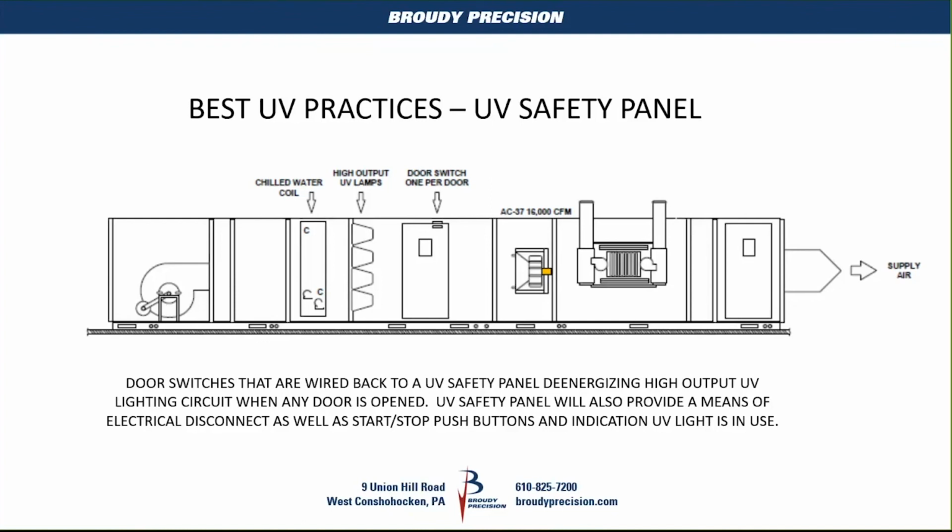There are a lot of units out there already that have UV lights. A lot of times you order a rooftop unit, and particularly in any hospital or medical center applications, they come with the units. So whether it's McQuay, Carrier, etc., UV is an option just like an economizer is anymore. So a lot of times that's there, and all they have is like a light switch or a little portal on the side of the unit to see how the light's burned out or it's on or it's off.